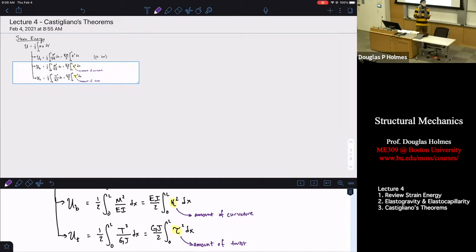Transverse shearing, for those of you who don't remember from mechanics of materials, is like this: take your notebook, and if you bend a stack of pages, you can look at the edge of that stack and you'll see that they slide past each other, right? The top one will slide. If I bend this thing a lot, the top one has slid up relative to the bottom one. Now imagine doing that little experiment again, but you glued every sheet of paper together. Now if you bend it, fixing that end, it wants to shear those pages past each other, but there's a glue or some sort of adhesive resisting that ability to slide. That stress that you store in resisting that shearing between those two pages is your transverse shear stress.